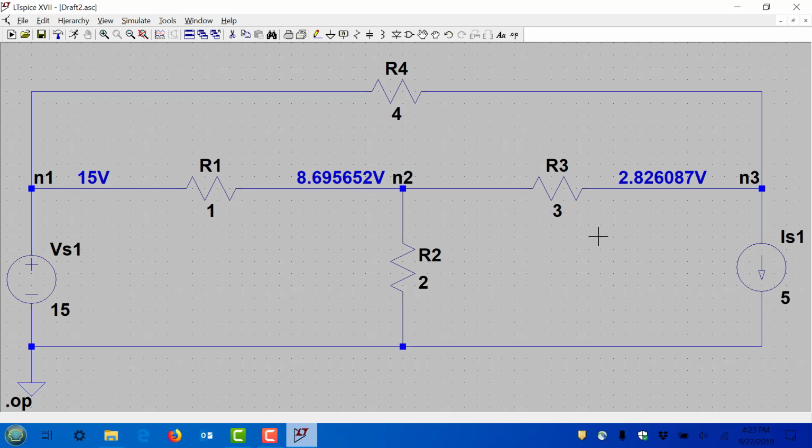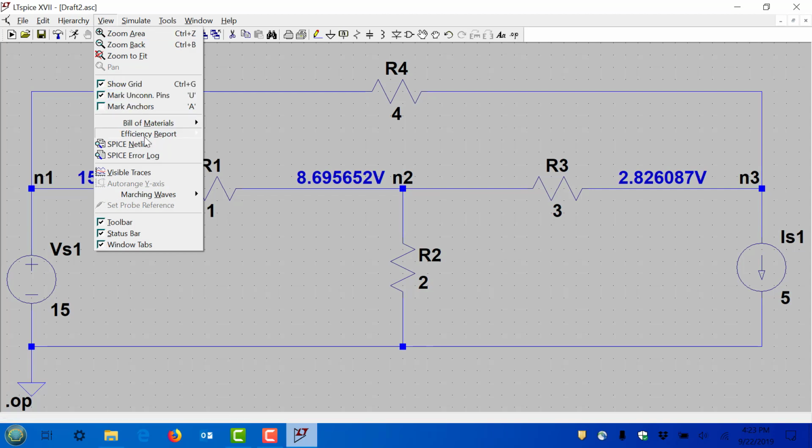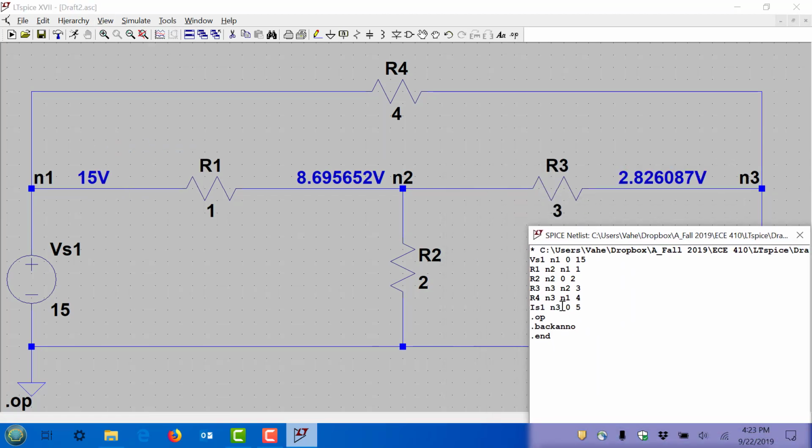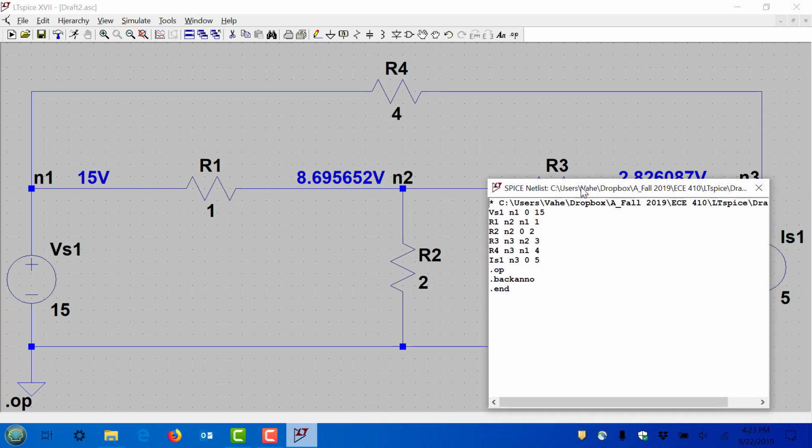So what does LTspice tell me? Hover over the component. It says it's minus 1.95, right? Now, why is it telling me that? It's because it must have this N3 first, then that N2. So it must have this node first, then that node on the Spice netlist. And it'll always report the current going from N3 to N2 for this one, right? Unless, of course, I flip it. I can flip the component and I can change the N2 and N3 if I flip the component on my schematic, okay? But now I'm getting into too much detail.